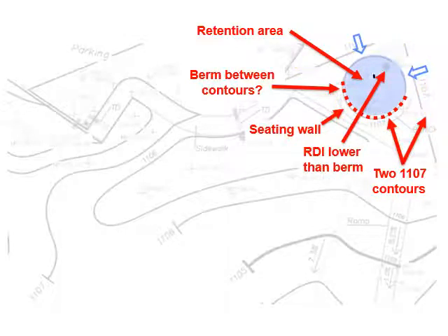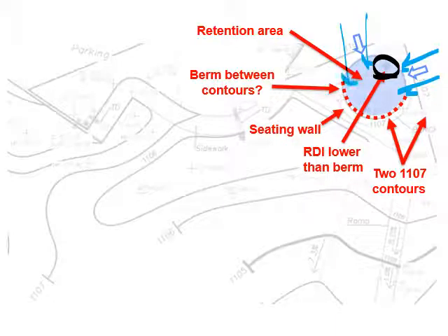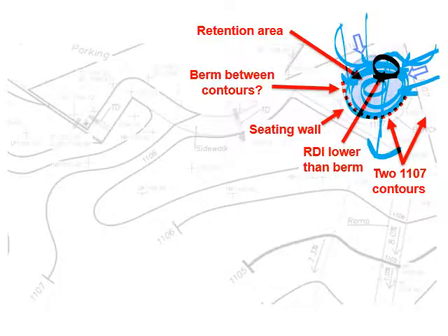And of course, we have a raised drop inlet. Again, that raised drop inlet is at the upper side of the retention area, so that the water that comes after the first flush is captured, the water that continues to come is diverted into that raised drop inlet and is allowed to flow downstream.